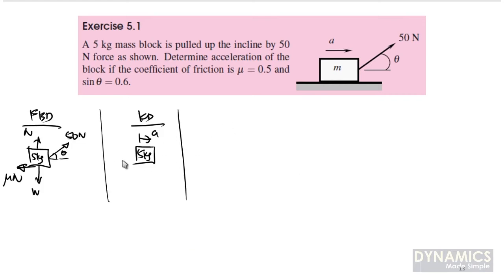Right. Once we have this, now we want to use our Newton equation: summation of force equals ma. For the summation of force part, we'll be referring to the free body diagram. For the ma part, we'll be looking at the kinematic diagram.